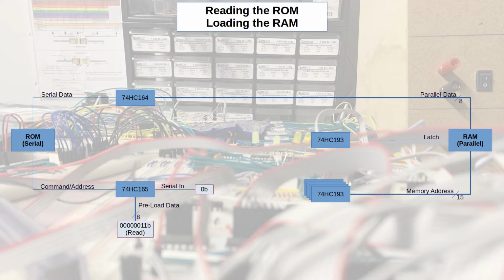Nothing that you see here, though, has anything related to orchestration built into it yet. It just shows how and where data is going to be moved around, but it doesn't indicate the timing. The first thing I want to talk about here are some of the control signals I'm going to need for each of these ICs to make sure that everything is kept in sync. Not necessarily how I'm going to shape those or determine the timing of them, but I want to get them identified so that I don't miss anything.